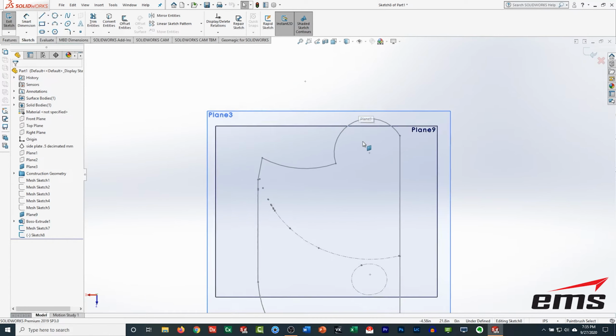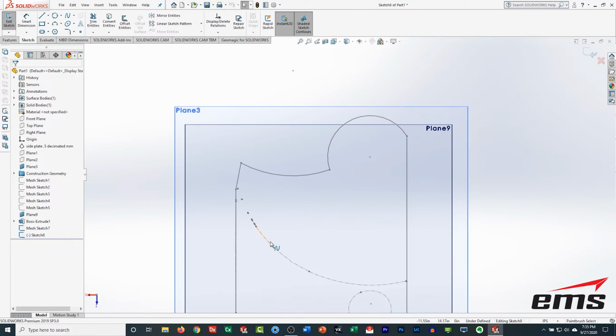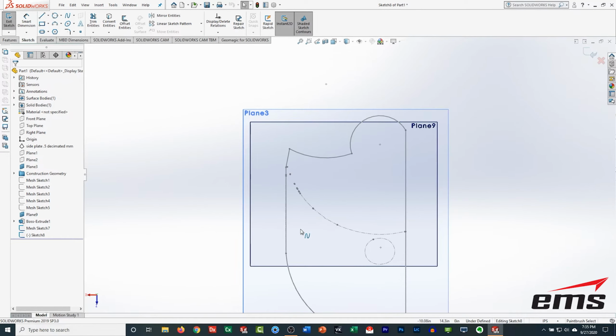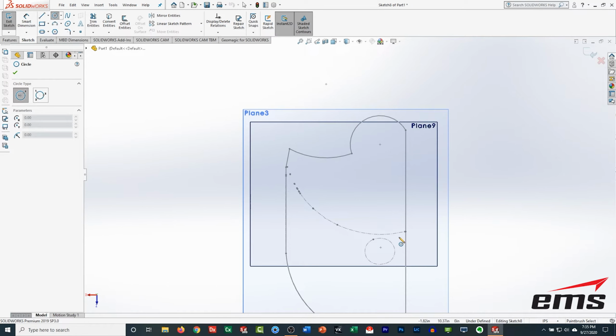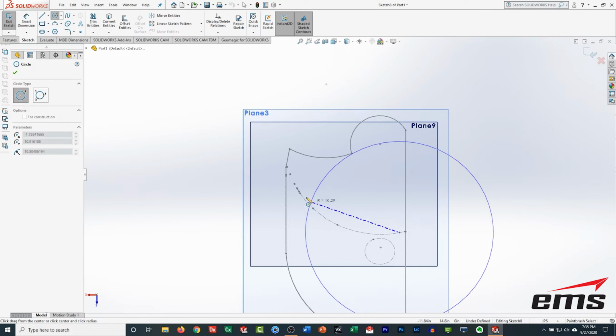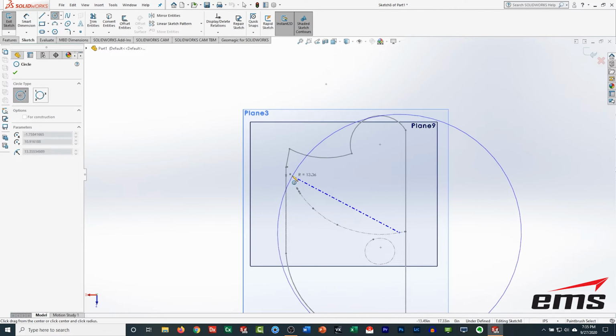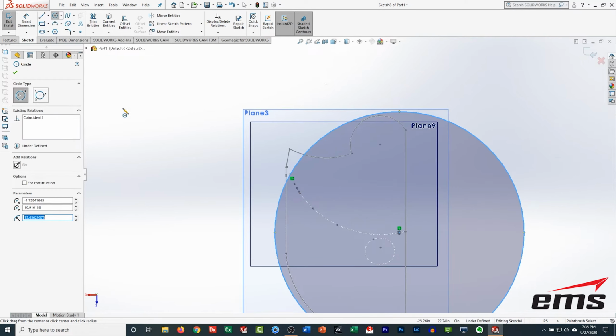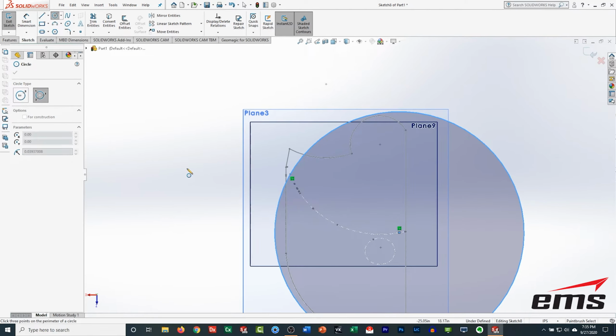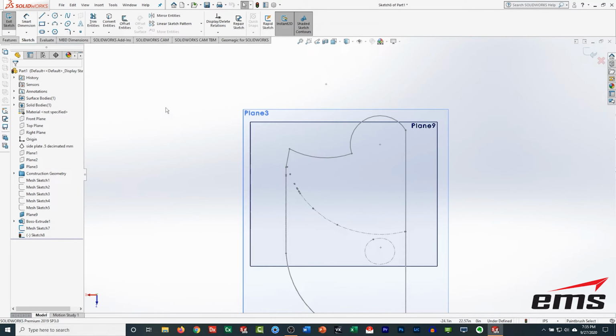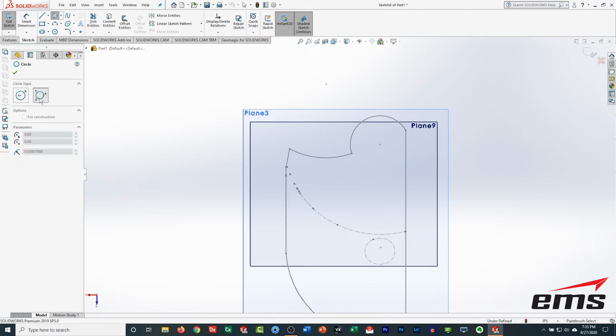So we want to cut this circle away, and you can see we've got a few spots where there is no mesh sketch, just because maybe there wasn't some scan data in those areas, but that doesn't matter. We have enough here to fit a circle. So again, we'll just pick on here. Oops, wrong circle. Let's try that again. Or wrong type. I want to do 3 points, so we'll pick,